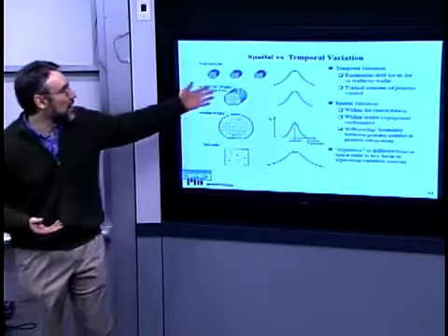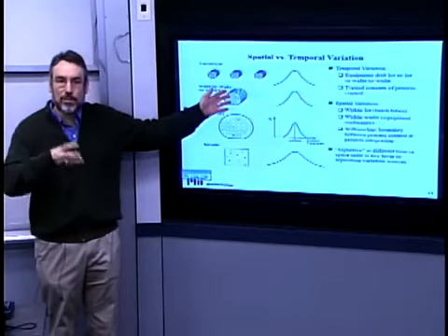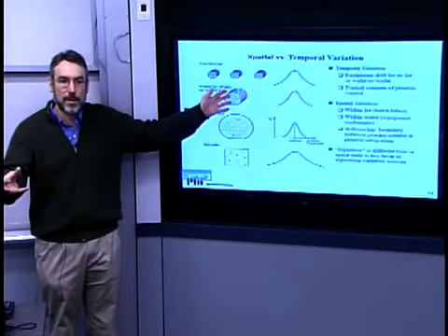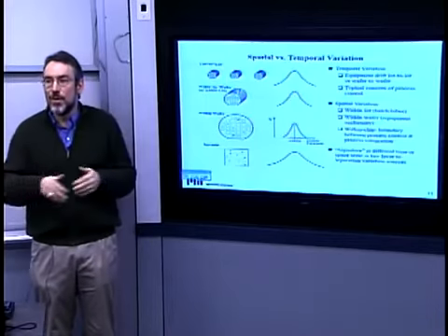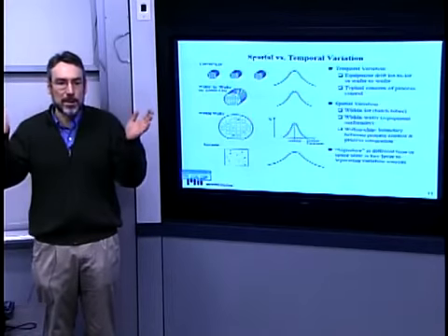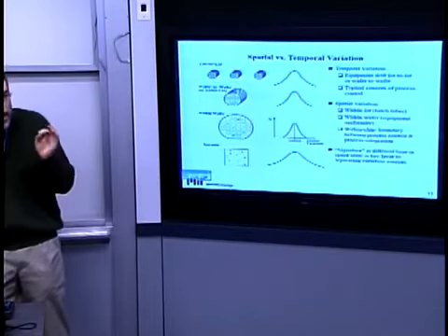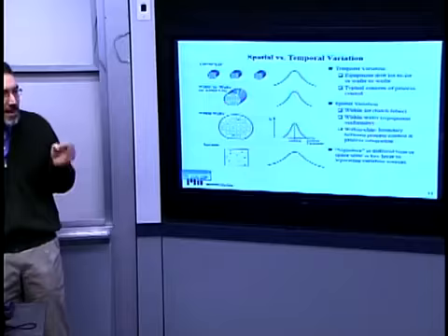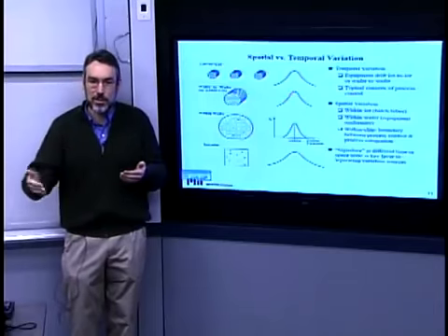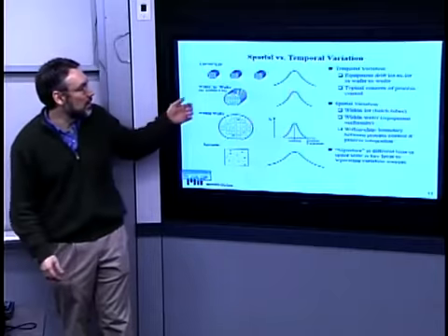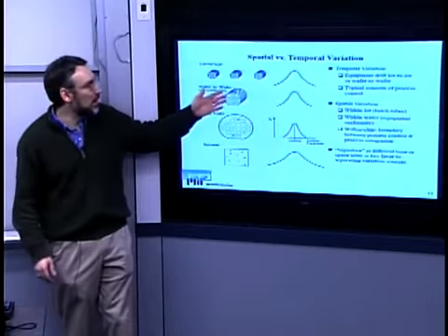And that might arise because of changes in the equipment state from one run to the next, right? The first wafer may have a pristine equipment with no buildup of material on the wafer wall. The next wafer might see a slightly different process unintentionally than the previous one because of changes or degradation in the equipment state over time affecting that wafer state. That might be an example.